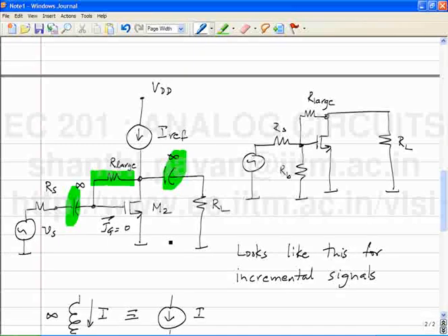On one side it is the transistor goes into the triode region, on the other side the transistor gets cut off. The cutoff limit is only dependent on the quiescent current of the MOSFET as well as the GM of the MOSFET. Okay. On the other hand, the limit of the triode region is dependent on, of course, it depends on VGS, it depends on VT.